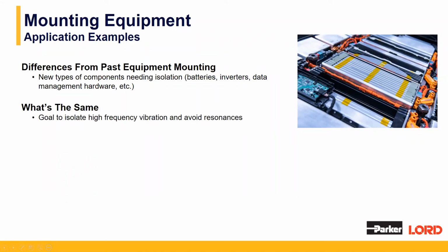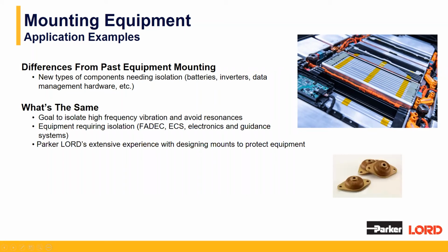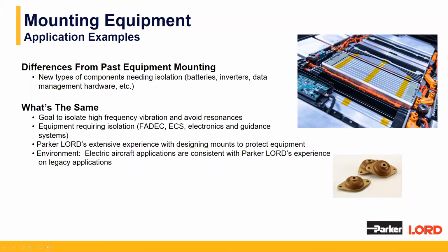Some things that will stay the same is the goal to isolate high frequencies that cause damage or accelerate degradation of the units being mounted. There's still many types of equipment that we see on traditional aircraft that will still require isolation, like FADECs, ECSs, electronics and guidance systems, PDUs, and the list goes on there. Lord's past experience with design for these types of applications, both relative to our knowledge and products, is not any different for these applications. And finally, environmental conditions. The environments we'll expect to see are no different from our past experience in rotary wing platforms, fixed wing platforms, military or commercial.